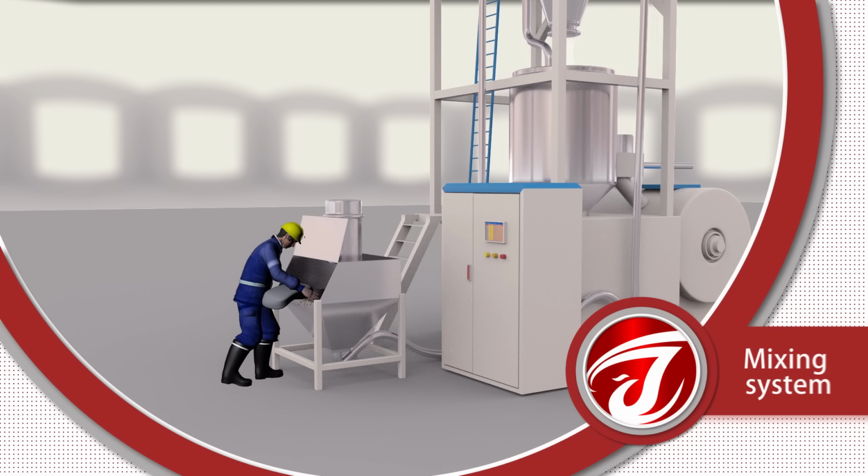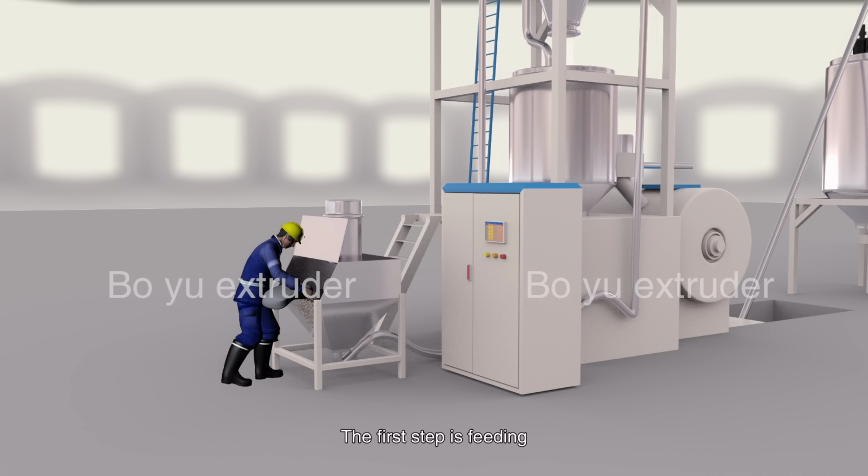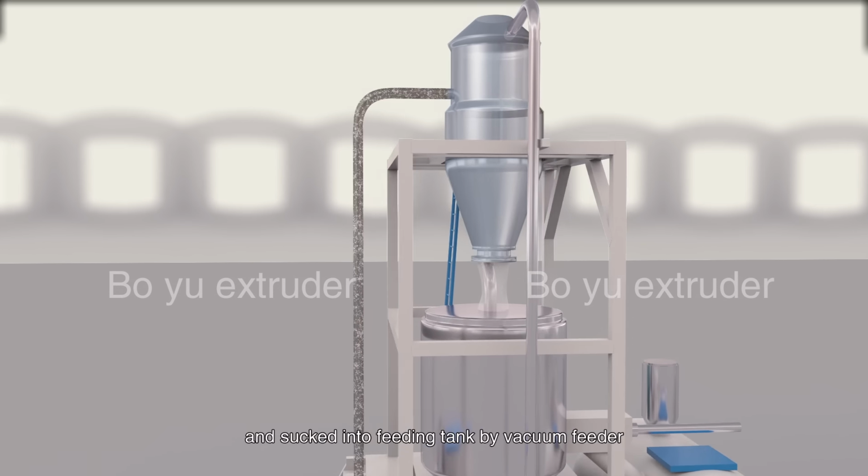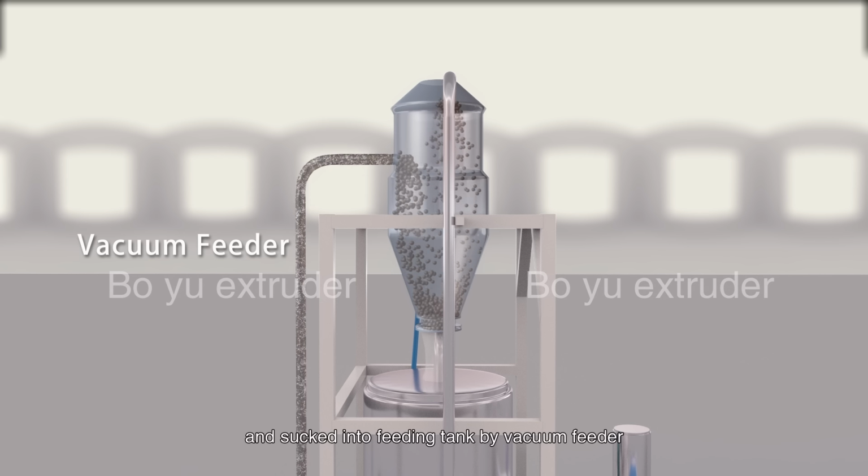Mixing system. The first step is feeding. The raw materials are put into the mixer in proportion to the formula. Other processing aids need to be weighed separately and mixed together. Then they are put into the feeding station and sucked into a feeding tank by a vacuum feeder.